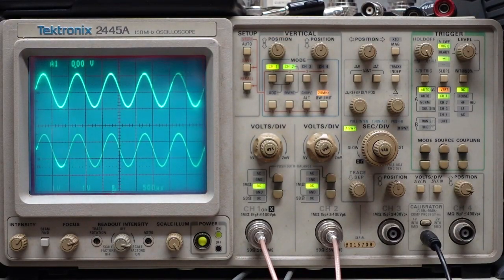Like I said, I work on a lot of stereos. This works out well for me. Now, when you're in 2-channel operation, you may have seen, if you have an oscilloscope or if you've looked at the front panel, a button that says Alt or Chop. Now, this is kind of handy, and it doesn't really come into play until you're looking at more than one channel. What it's talking about is the sweep of the oscilloscope.